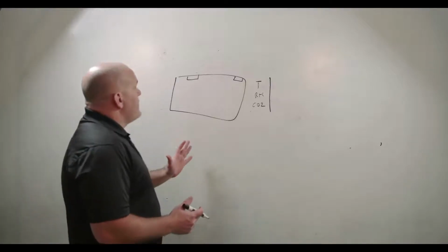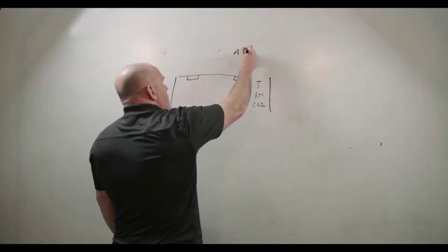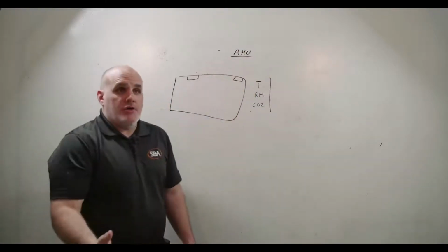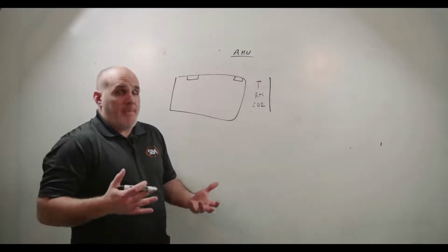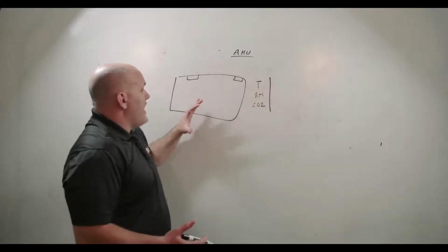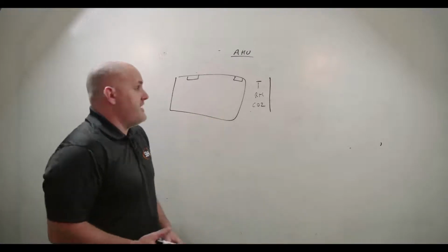There are three main ways that we do it. We either do it through an AHU, an air handling unit. An air handling unit may be 100% outside air, maybe a mixed air unit, maybe a packaged rooftop, feeding directly into the space, a one-to-one relationship.